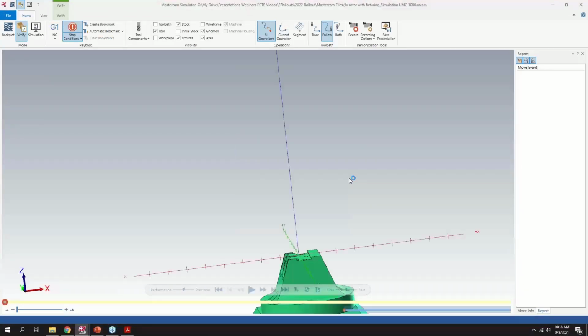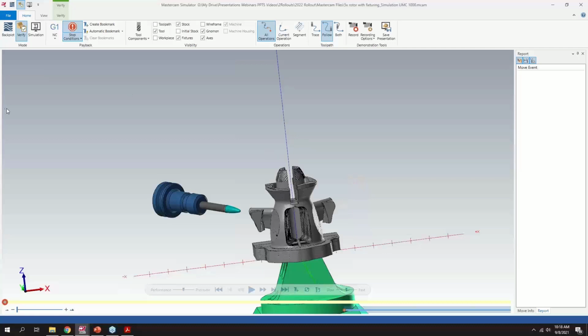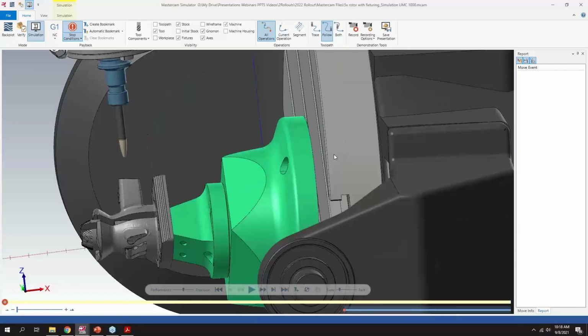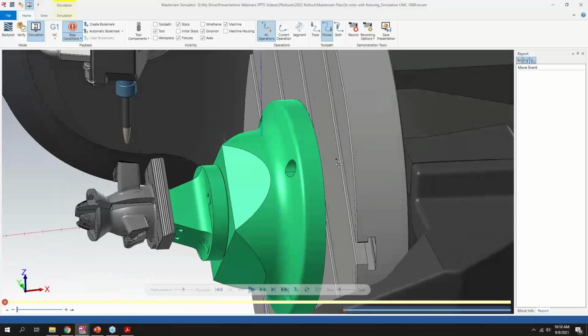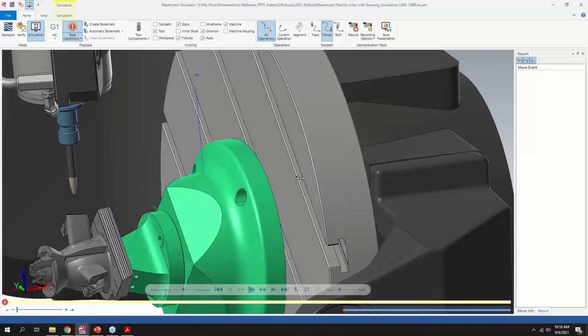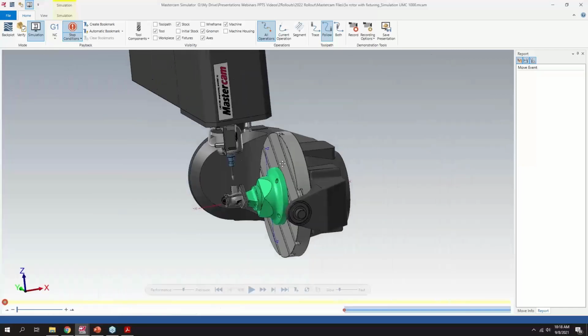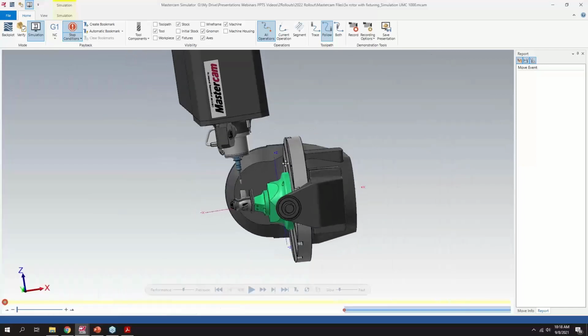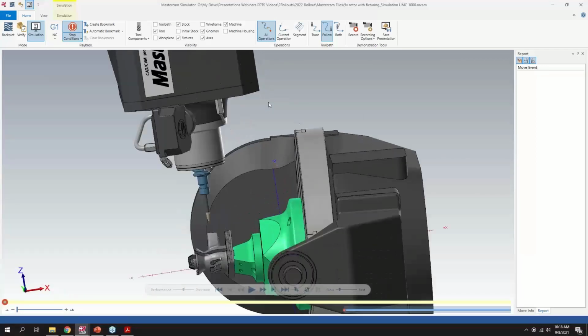And then once this loads up, I'll show you the other handy way that this measure tool can be beneficial, especially when doing any sort of machining where you're concerned about proximity distances. So now I can see that work holding is nice and flush with my table of the machine. Now, as you can see, based on this file setup, I'm pretty deep with the spindle relative to the table to machine this blade here.